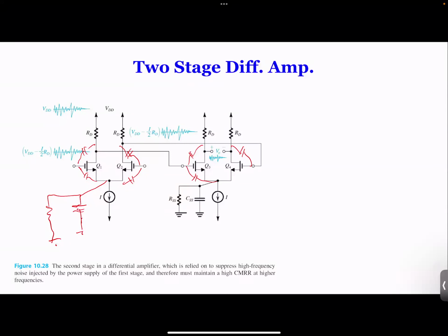If you go to our lab, when you do any experiment, 330, 430, whatever, you look at any power supply and you use your oscilloscope to measure the DC. If you use a multimeter, you don't see it because it gives you a number. But if you use an oscilloscope to measure the DC voltage, you have a straight line initially, but keep increasing, reduce the time scale, keep increasing the time scale, and you will see it start to have some noise coming.